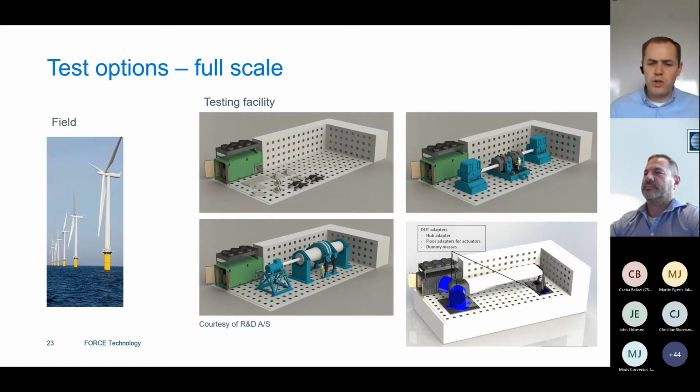So what we're trying to do in the test bench is create a representative setup, a testing case for how we can shorten that 25-year lifetime into a much shorter testing time, usually something around a few months. And we do that by scaling the loads, taking those very small variable amplitude loads over 25 years, shortening them and making the loads bigger to be able to accumulate the same kind of fatigue damage.